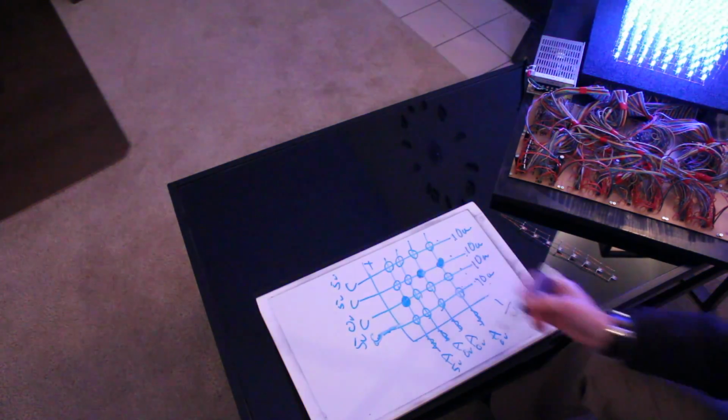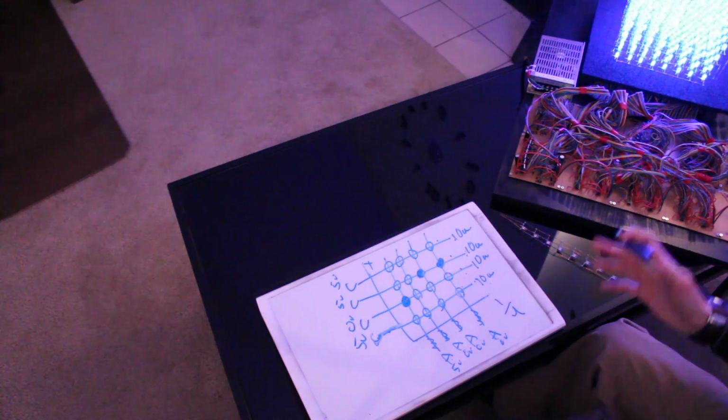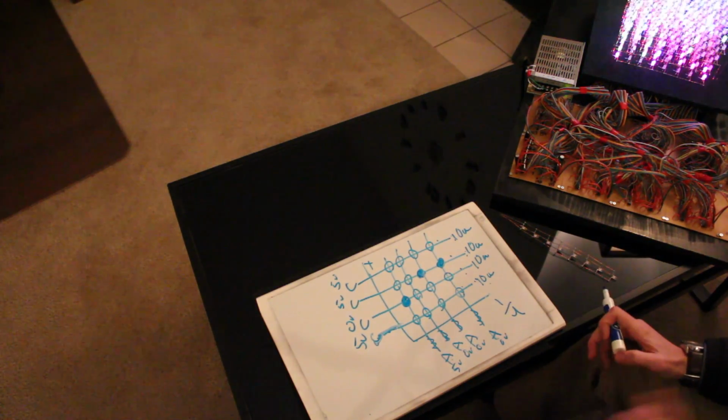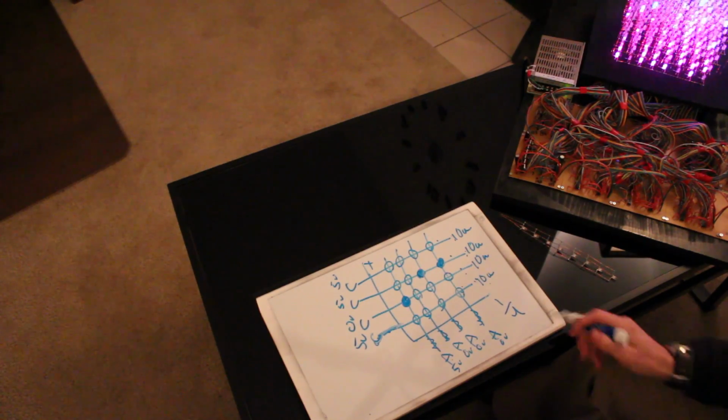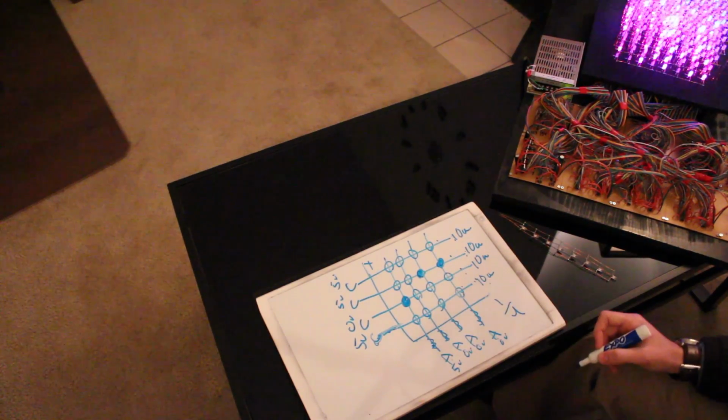So the best these LEDs here can do is a 25% duty cycle, which isn't too good, really, if you think about it. So one technique they do when you're controlling this many LEDs is they'll lower the current limiting resistor.